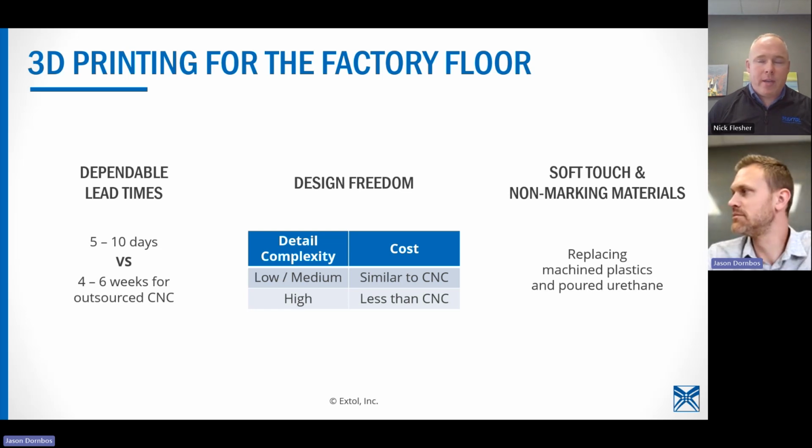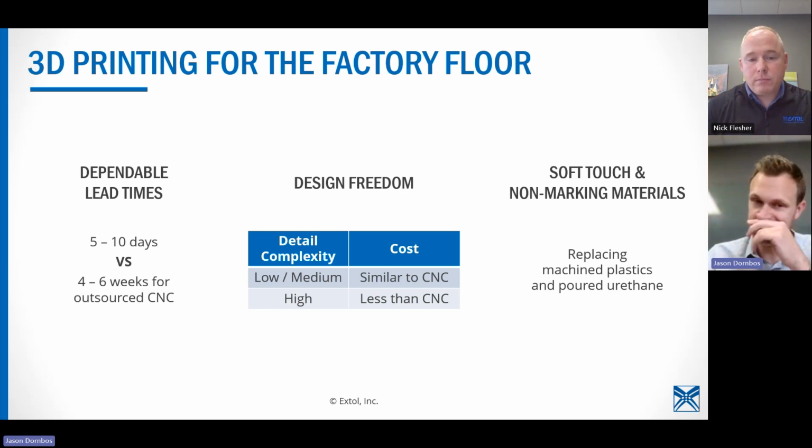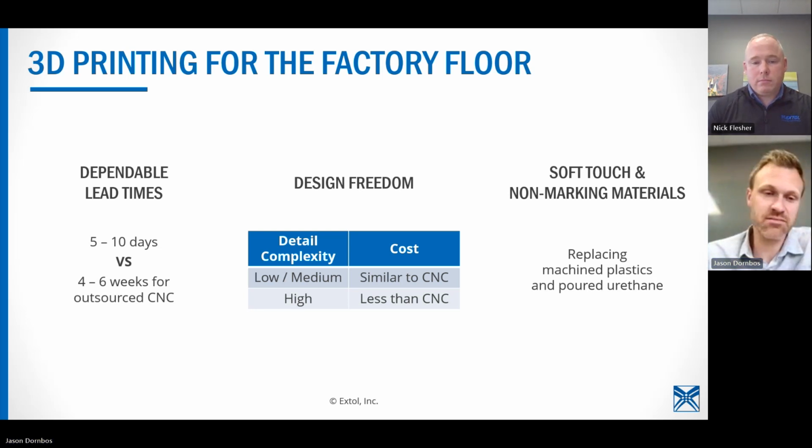We've seen it for clip driving and some other things where you implement sort of manifolds right in the tool itself. So you can lightweight end-of-arm tools, which can be a big cost driver if you've got to upsize your robots for big heavy tool weight. Yeah, with 3D printing, design complexity is free. So features that you can print into the detail, the better.